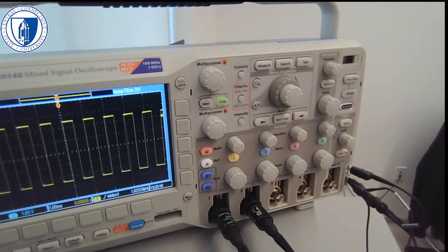And now it's nice and static, and that's happening because the trace is starting at the same voltage every time. Because it's starting at the same voltage every time, and because the waveform is a nice regular waveform, it looks like it's stationary. It's not. It's going across lots and lots of times a second. But because it's going so quickly, we can't see it.